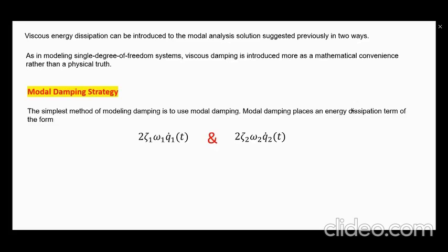Now, when we have a 2-degree of freedom system, the mother of all equations will be a diagonal mass matrix times the second derivative of the modal degrees of freedom, plus a diagonal stiffness matrix times the modal degrees of freedom. What we did in the last 2 days is we carefully eliminated the damping term. The damping term in the mother of all equations is C x dot.